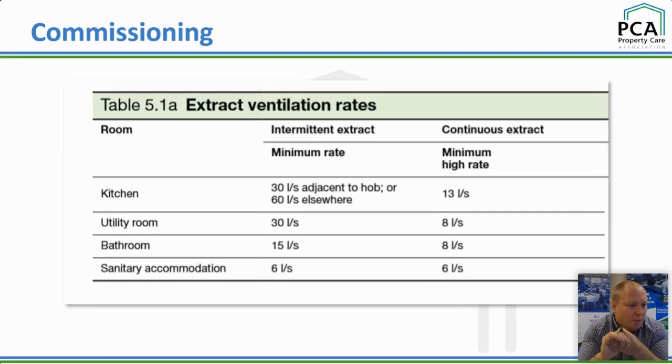And I think this is part of the problem, and why we're seeing the compliance rates that we're seeing, is that too often the ventilations are installed by people that don't appreciate they've got to be a competent person for Part F as well as Part P. The other exceptions for not notifying in advance are if it's minor work, so you're looking at sort of like-for-like fixing fans, things like that, or emergency works.